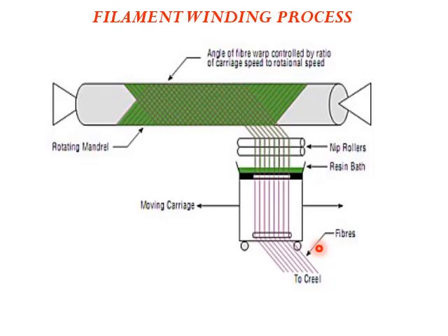By controlling the ratio of this rotation to this linear motion, we can control the distance at which we wind these fibers on the mantle. This is something like the lathe movement, where we have the carriage linear motion and rotation of the workpiece. Depending upon those, we can calculate the feed at which we wind these fibers on the mantle.